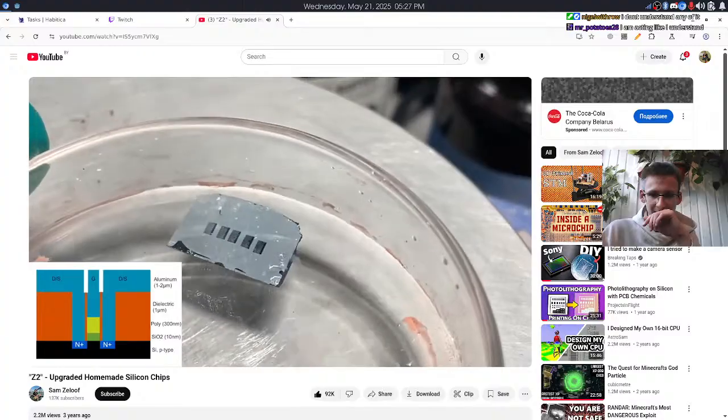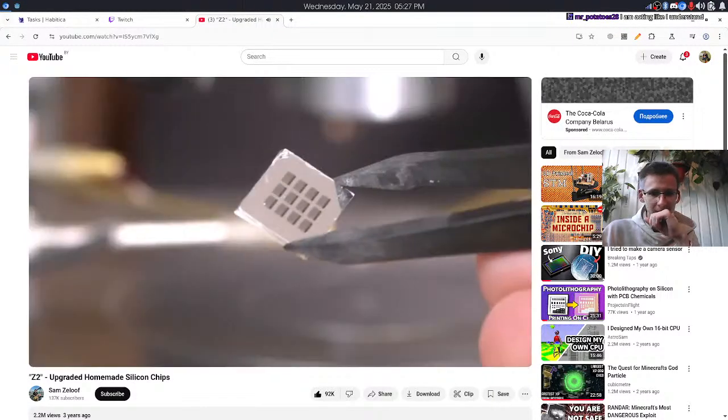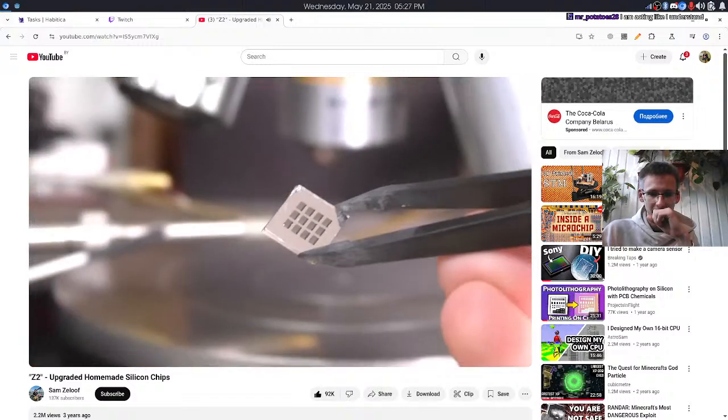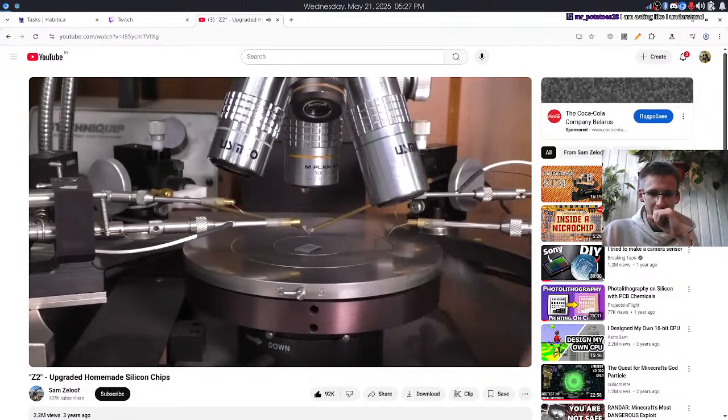the chip is done. At this point, I'll inspect the chip pretty thoroughly and take a lot of close-up pictures to measure parameters like gate length and width and layer thicknesses if I do a cross-section. I can put it on the probe station, which has a bunch of really small tungsten needles that allow me to make connections directly to the transistors.